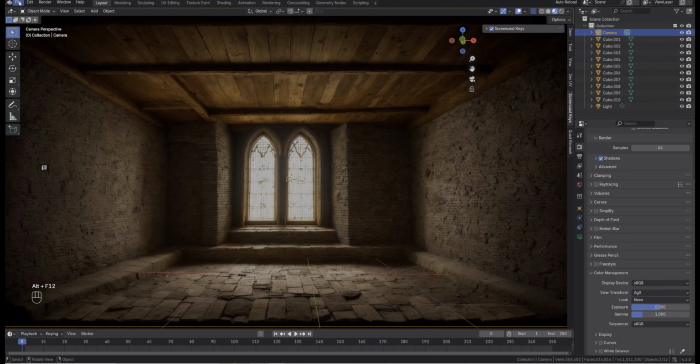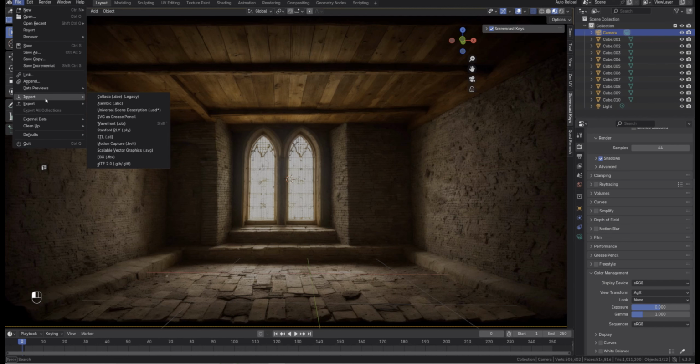I go inside Blender, File, Import, OBJ, and we pick our OBJ. Press G and move this around. It looks like it's not exactly in the right position or scale. So let me rotate it and put it in place to scale, and move it around there. And we do need to connect the textures.